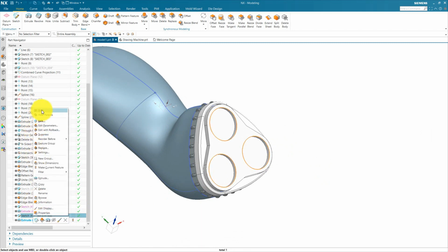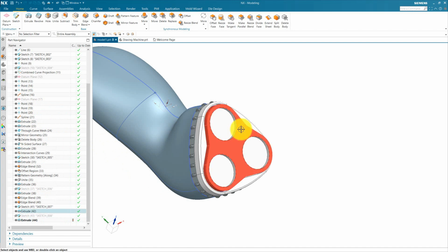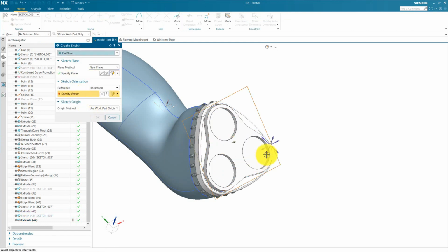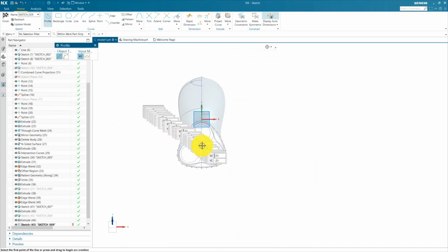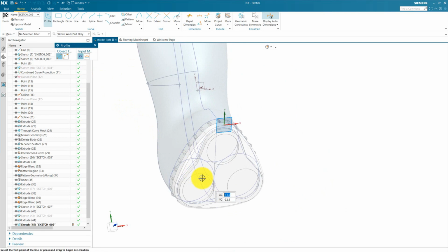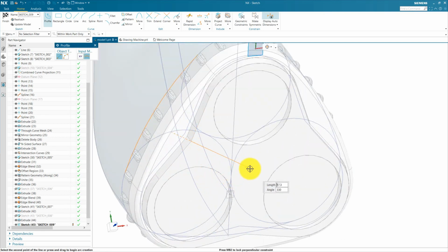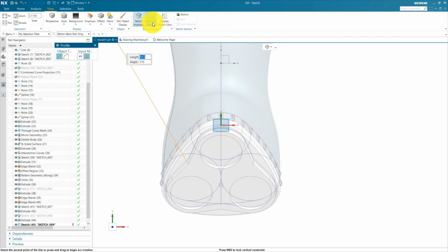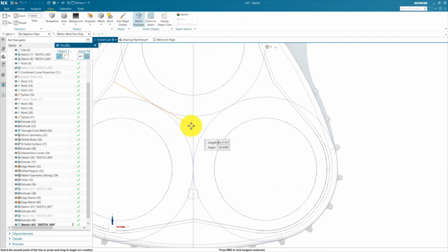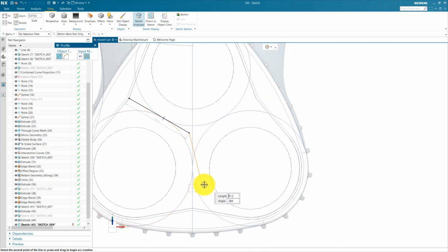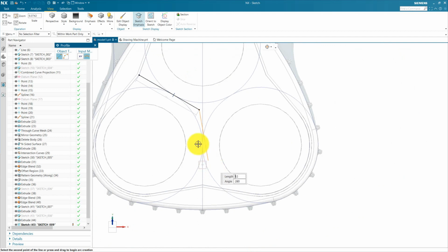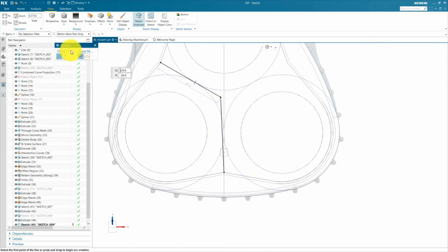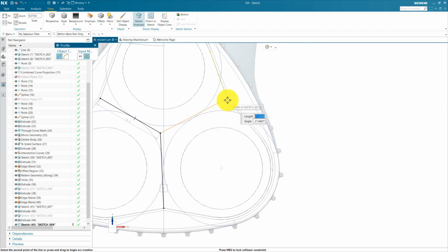Hide this section. Next we are going to create a sketch on top of this extrude. Select again the face and the horizontal reference, press OK. Now we create a sketch from this point to center. View, sketch orientation, select the center approximately. After that we find the exact center: when we make the lines equal, it will automatically get the center. I show you how.